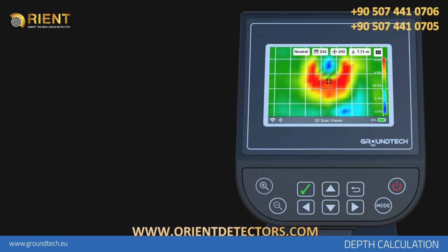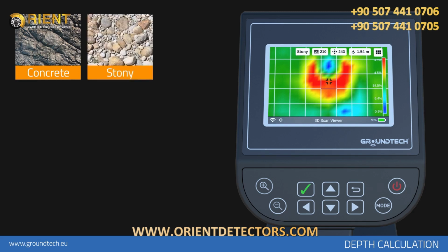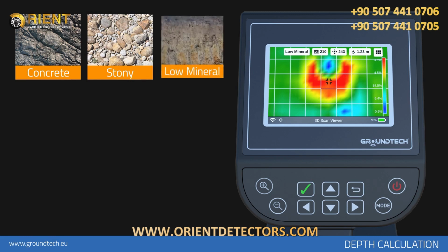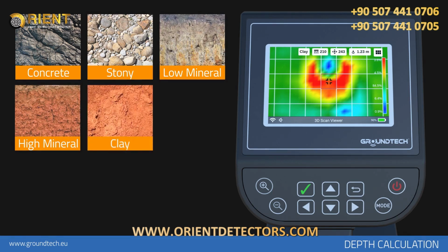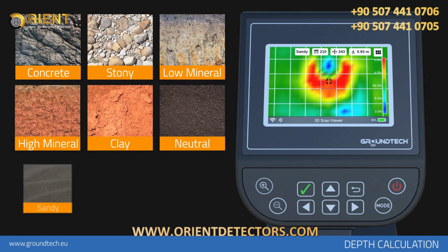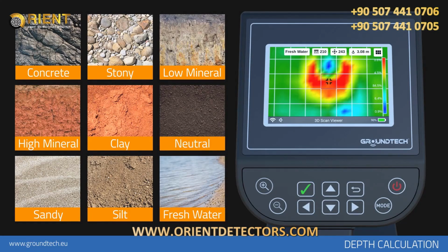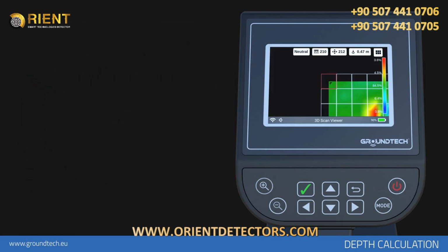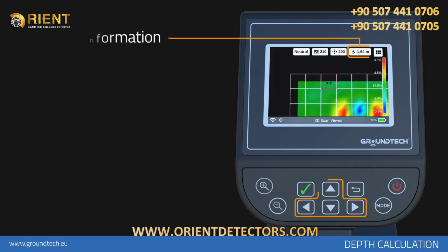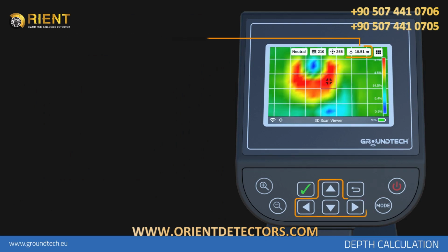For example, if the area you are working on is completely rocky, choose Concrete. If it is stony, choose Stony. If it is non-mineral, field-like, choose Light Mineral. If it has high mineral concentrations, choose High Mineral. If you have no information or estimations about the type of soil, you can make several calculations in different options and compare them for a more accurate calculation. After you select the type of soil, you will see depth information for each point on the top bar as you go around the graph with direction buttons.